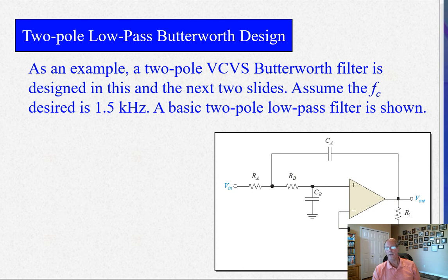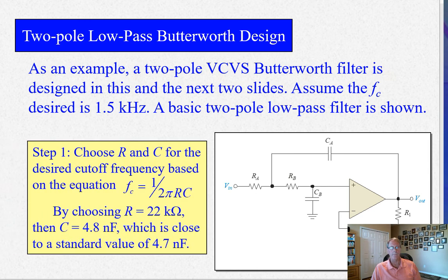So, is this a high-pass filter or a low-pass filter? Now, it says it's a low-pass filter, but let's take a look. What happens at high frequencies? Well, immediately this capacitor shorts out. So your signal input to the non-inverting input goes away. So immediately you know it's at least a low-pass filter. All right? In a similar vein, this capacitor shorts out, which further reinforces this capacitor in bringing the signal down. All right?